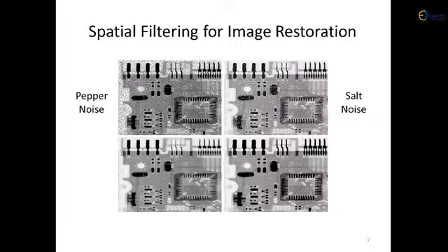You can see on the left-hand side that most of the image portion is affected by the black dots. So this is just like the pepper here. When we represent the image intensity, the pixel intensity from 0 to 255, in the 8-bit environment, 2 to the power 8 gives 256 possible gray levels or intensity levels. So most of the pixels are intentionally made dark dots to represent the lowest possible intensity level, which is 0 here. So this is nothing but the pepper noise.